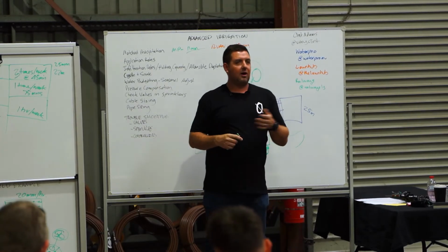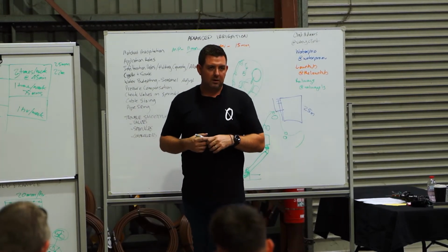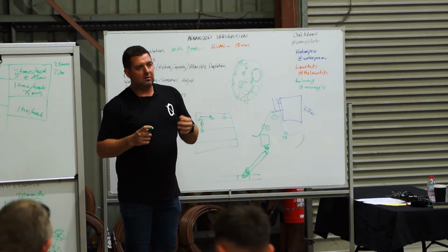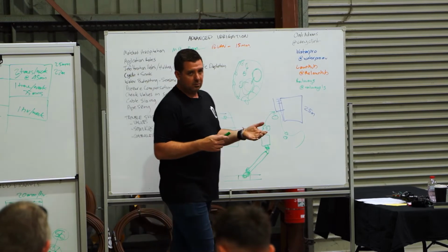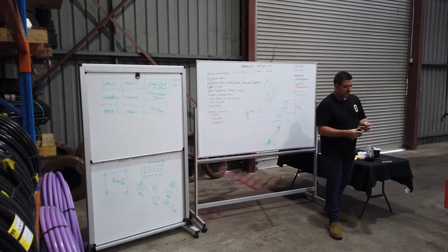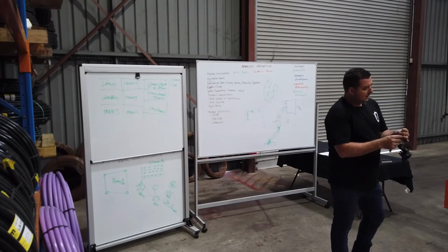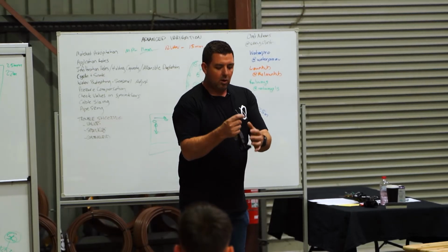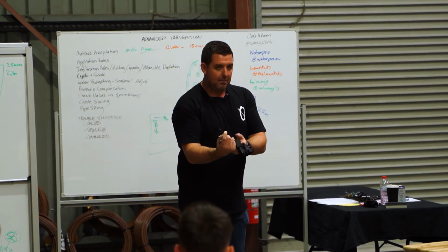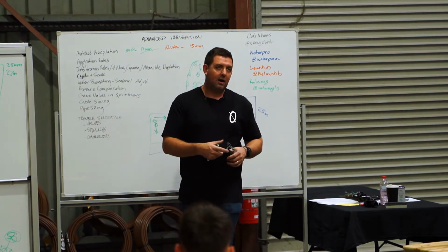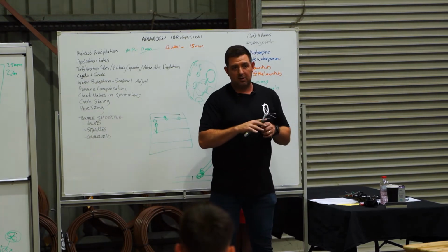So this is a chart that we use when we're designing commercial irrigation systems to work out how far a certain gauge cable can run before the solenoid valve's not receiving enough voltage to open. So the way a solenoid valve works is by sending a pulse through to these two cables. It's an alternating current. I'm talking 24 volt solenoid valve AC. It's an alternating current, so it doesn't matter obviously the polarity. You wire that up, it sends electricity through to there, an electromagnet lifts the pin and it opens the valve. Now, if you can't get enough electricity to these valves to do that, they're not going to work.